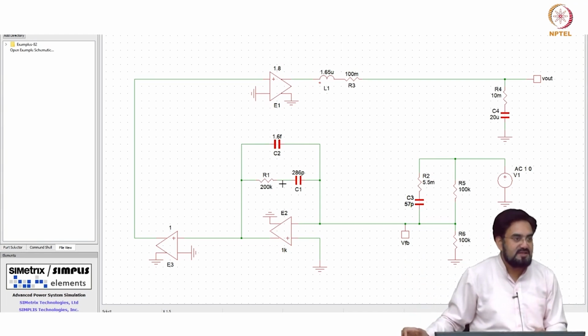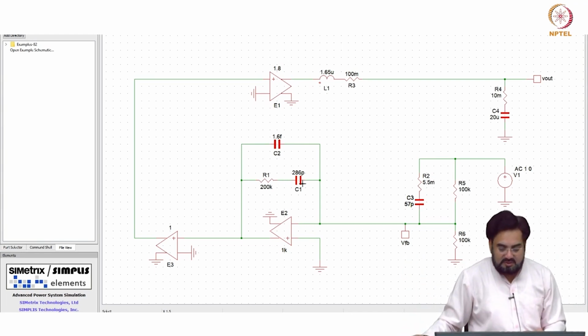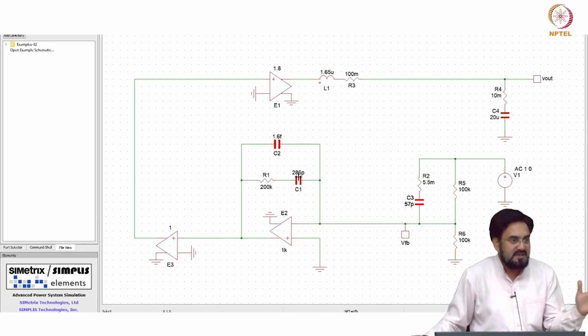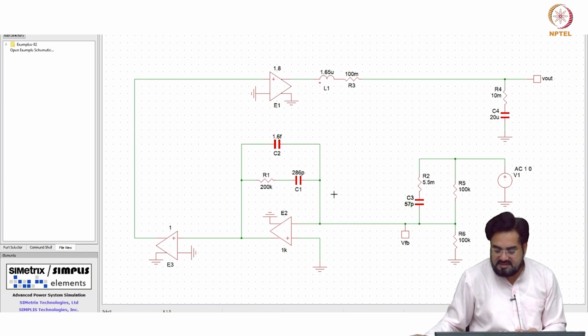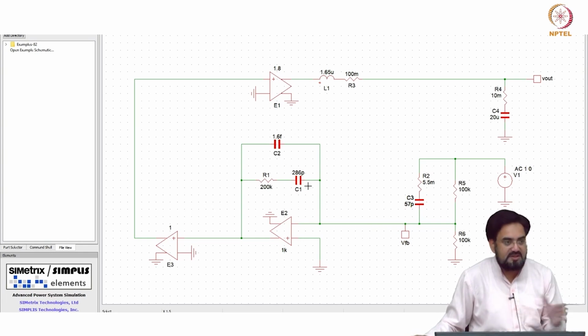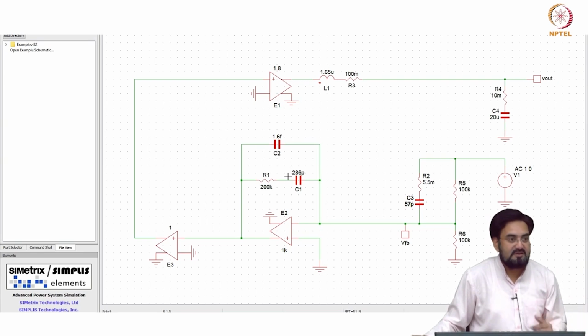So, now Ki needs to be adjusted. If you change this capacitor C1, which is the integral cap, it is also moving your 0 inside. No matter what the value of this cap is, your proportional gain is decided by R1 and this feedback resistor. So you are not affecting proportional gain here, and that is why, if you move your 0 inside by simply changing this cap, it only affects your integral gain. So your omega UGB will not get affected.